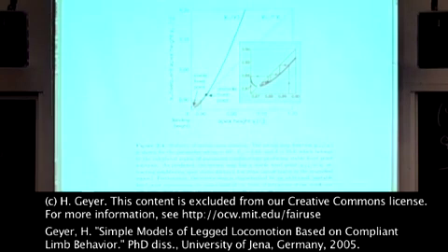Seems you always land the same angle. That's pretty much exactly the issue, your failure mode can come from coming in, squishing really low. I'm going to fall on my face here, so I should let everyone see it. You can compress and get really low, and then you bounce forward. And if you bounce forward at such a trajectory that you never get high enough for your leg to be out, touch it down, then you're just going to bounce forward, land on your face, and you can't actually swing your leg. Does that make sense? So you bounce in, you shoot across, and if you never have an apex high enough, you'll never get your leg ahead of you. So that's the failure mode. That's actually what we see when we simulate it.